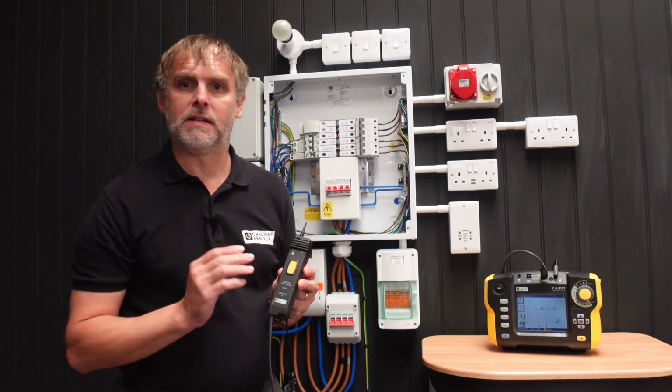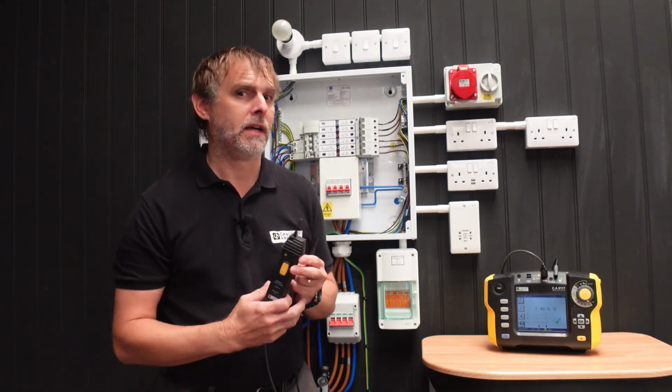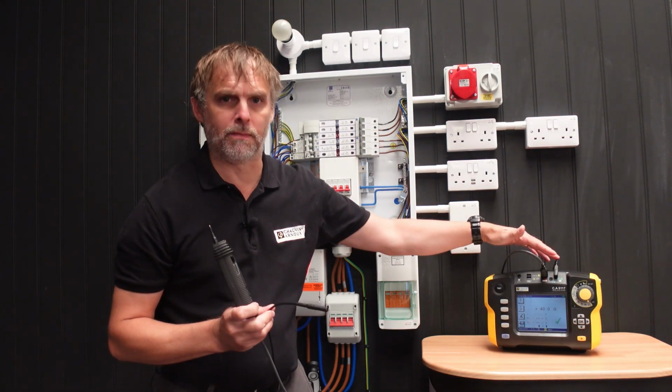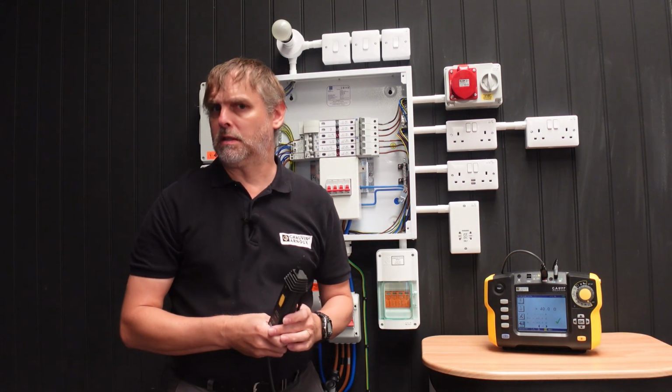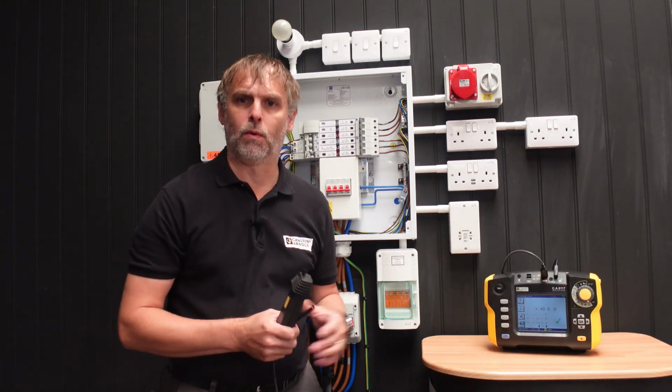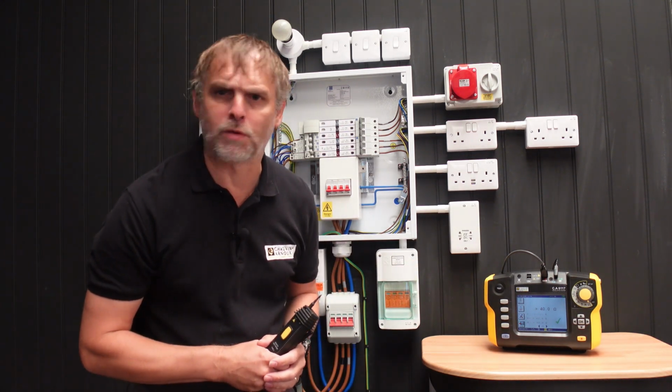When undertaking a physically awkward to reach test, the remote probe with integral torch and test button may be employed on dead tests such as resistance and continuity in conjunction with a lead in the COM terminal. This concludes the resistance and continuity functions of the 6117, but this instrument does a lot more than that.